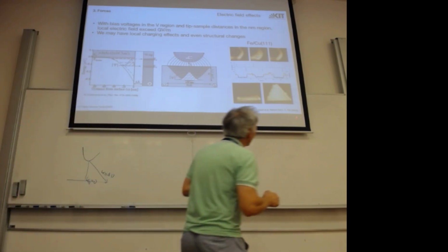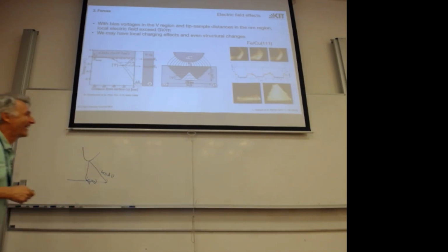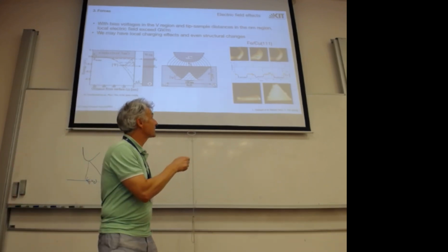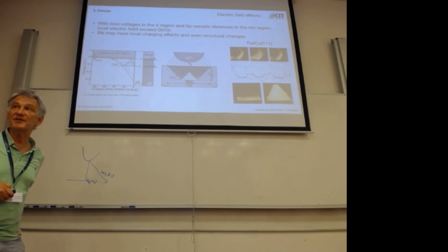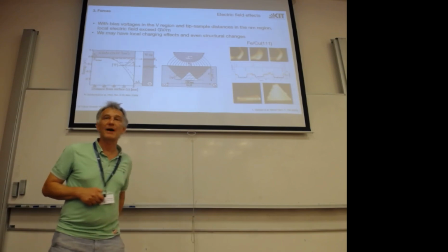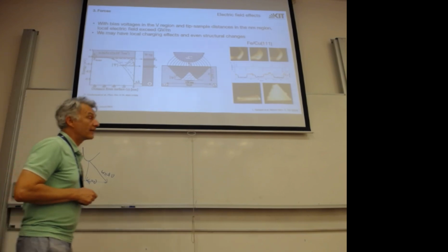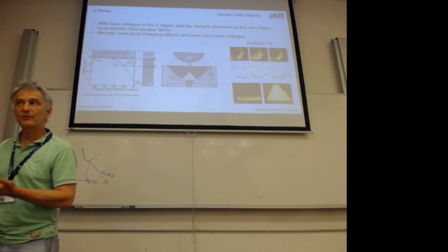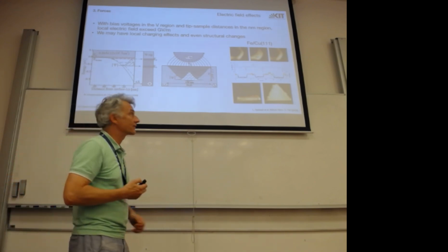It's already a long time ago. Oh, I'm getting old. This was an example of iron on copper. Now I should say iron is a complicated material because it has two modifications, FCC and BCC. BCC is the normal modification at room temperature, it's a ferromagnet, and FCC is an antiferromagnet. They differ only a little bit by an expansion of the lattice. It's a martensitic phase transition without actually diffusion happening, just expanding the lattice.